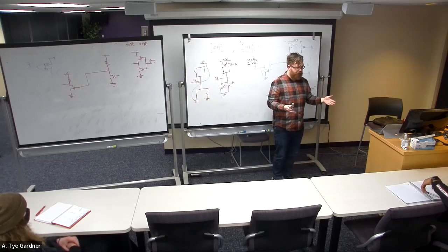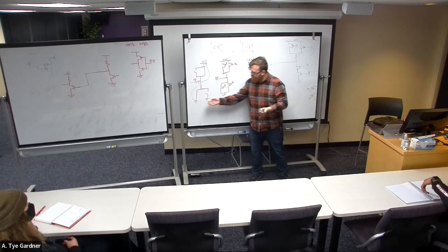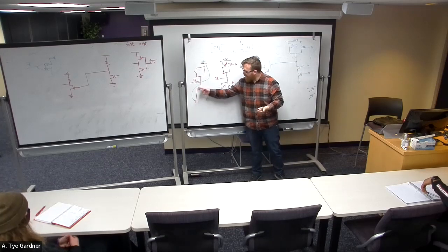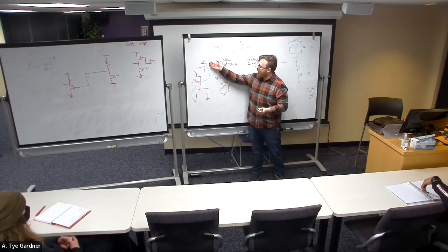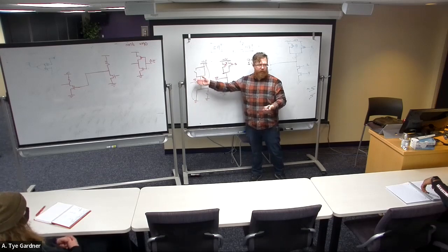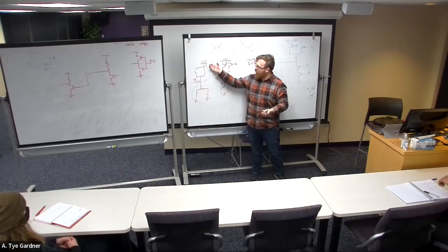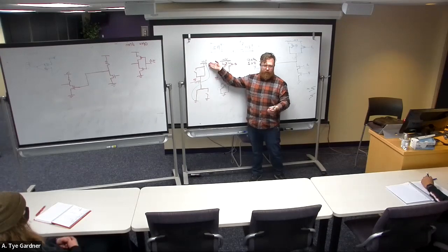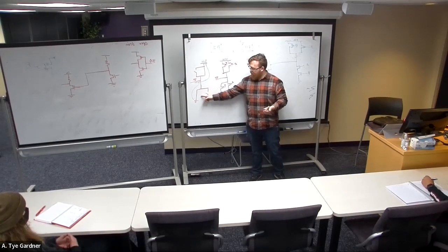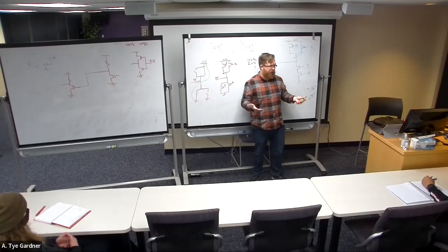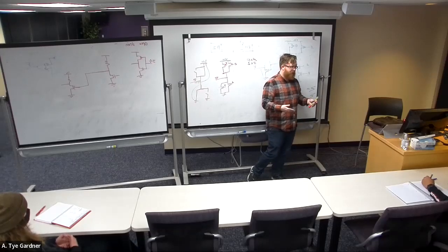It's all the same voltage, but ground is 0 and connected to this whole node, and VCC is power and connected to the whole node. So VCC is trying its hardest. It will put every ounce of energy it can to make this 1. This path will put every ounce of energy it can into making it 0. And now they're fighting. Okay.